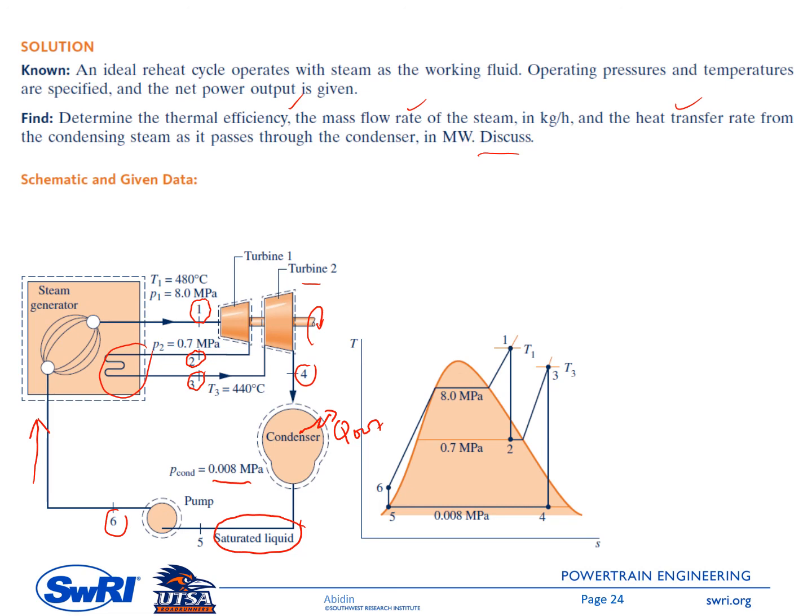If the saturated pressure is higher than 80 bar, okay, then the condition is superheated. Similarly, you can also use table A3. It is a pressure table, and check what is the saturated temperature at 80 bar. So if the saturated temperature is lower than T1, then the state at point 1 is superheated.